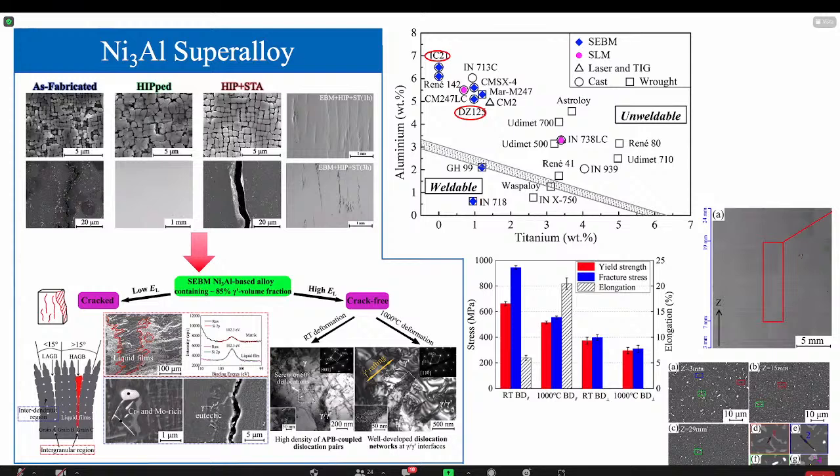Yes. So when we use the very high energy, what we tend to get is a very fine columnar structured material. And we also did some parametric study. So when your energy is very low, again, you tend to have these very refined columnar grain structures. So there is an optimum condition where you can get a very large width in terms of the grain. You can get these coarse columnar grains. So this can be manipulated depending on the energy input you put in.